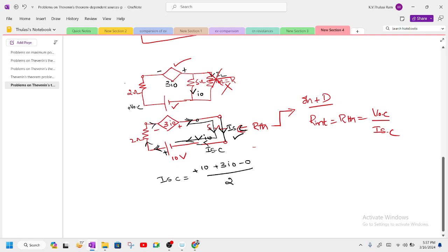Okay, 2. So already from the problem it is clear that whenever you have a short circuit, whenever you have a parallel branch with respect to one branch with high resistance, automatically current will flow only in the low resistive path. It doesn't flow in the high resistive path. Therefore, it's very simple to understand. You have one 5 ohm resistor, you have one short circuit path, R is equal to 0, R is equal to 5 ohm. So generally if you do by layman method also, you'll be getting the same. You can see here.